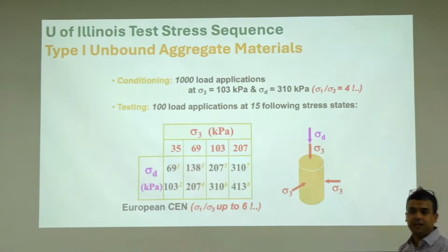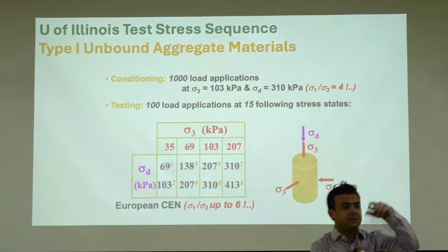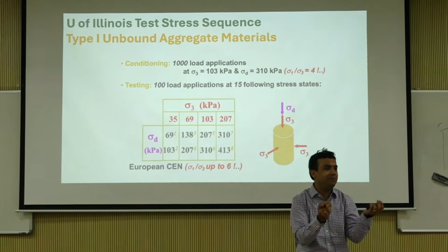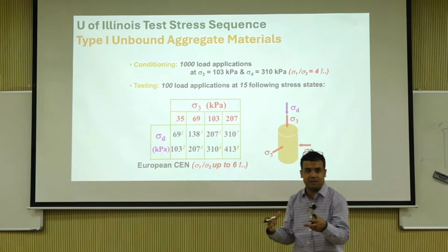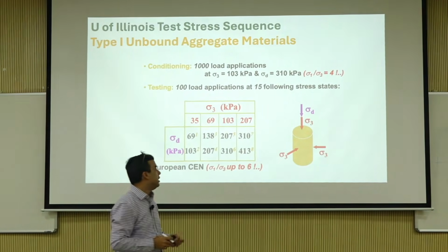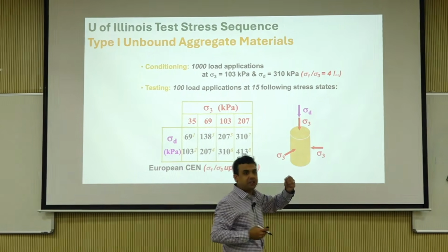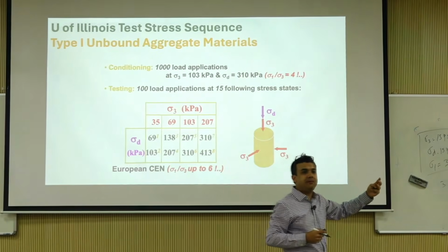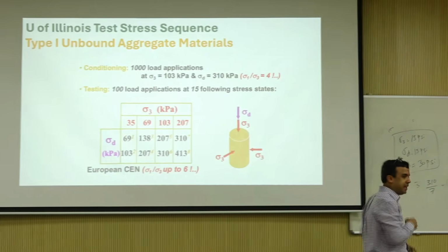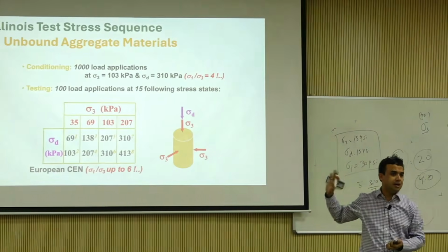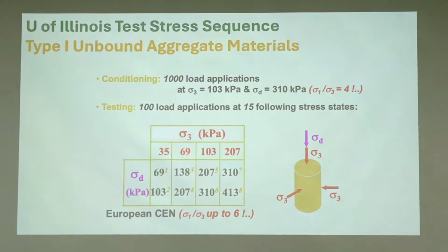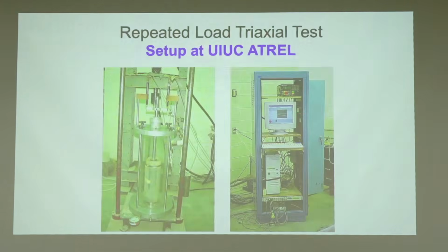Remember yesterday how we calculated subgrade soils? They are not very well confined, because it's only about half a psi of confining pressure we calculated yesterday. The whole idea is that during compaction, the more you push it, the more you condition it, the more of a resilient behavior you will get. So that is how this was defined. Again, this is a research test method. It is not a specification. It is not written in AASHTO. It was just a research method that was developed.